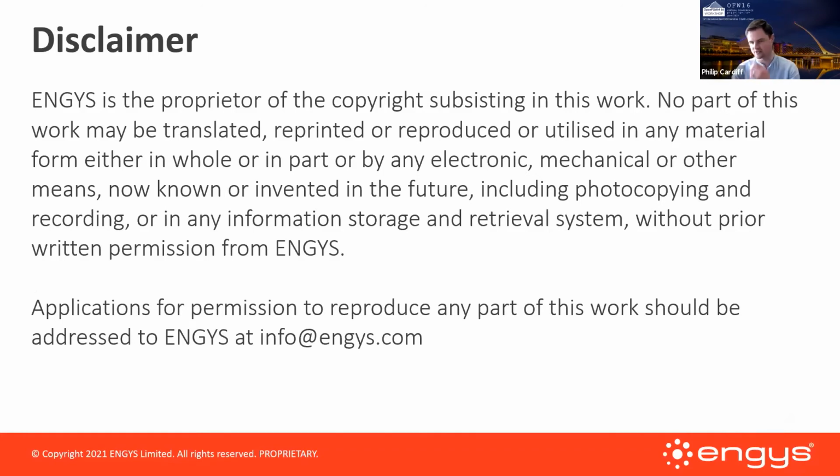I've got lots of questions that I'll start with while people are typing questions. Why are the results slightly different for the block coupled solver versus the segregated solver? Why are they not exactly the same? It depends on the level of convergence that you achieve. The structure of the solver is the same, the underlying boundary conditions and so on. It's just that the coupled solver converges better.